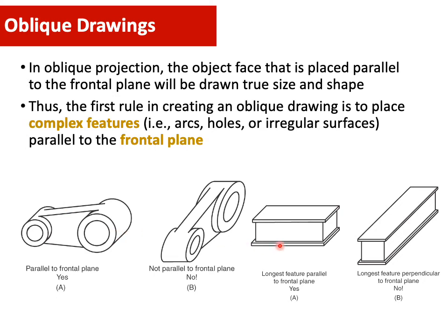Also for this one, the longest or widest side needs to be facing you. It can't be on your right side. You need to have it in the front view. You need to remember the complex features, or even the widest, need to be at your front view. So you need to remember these first rules.